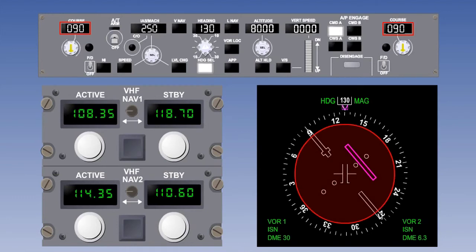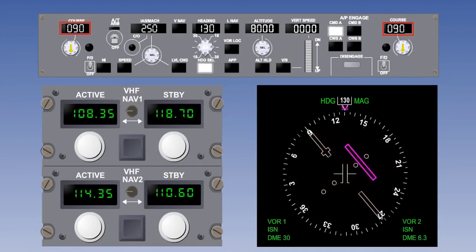This positions the course carriage on the HSI, EHSI, or navigation display. The deviation bar and scale show the angular deviation of the aircraft from the selected radial. When flying manually, the pilot would assess the rate of closure to the required radial by looking at the movement of the deviation bar and turn the aircraft at the appropriate time to intercept the radial.